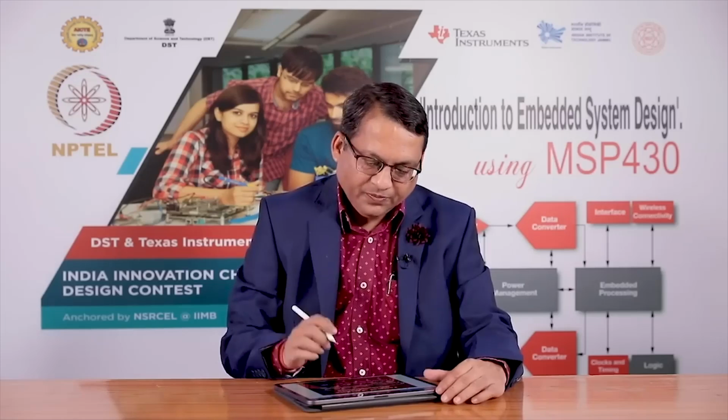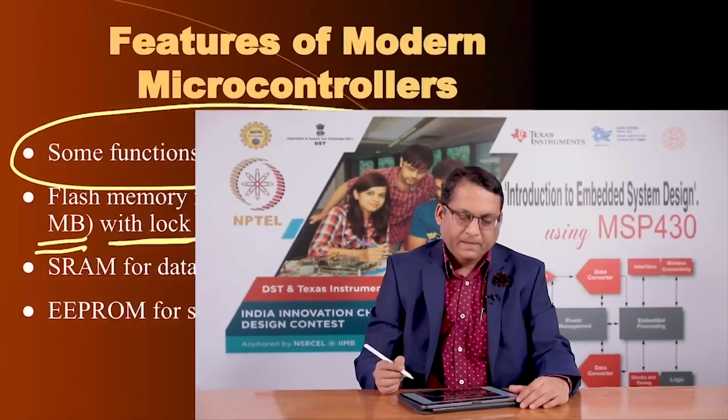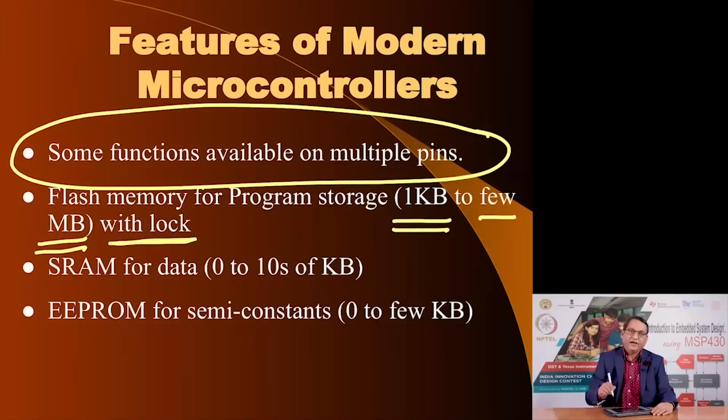Therefore, a better method is to use microcontrollers with integrated program memories, especially which have a lock function. You can invoke this lock once your program development is complete. You can secure the contents of these memories by selecting the lock feature, and thereafter nobody would be able to read the contents of this memory by connecting to the programming pins. This is a very important feature to consider, especially when you are making a product.